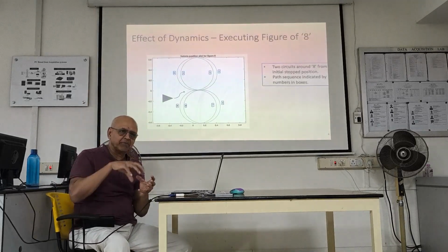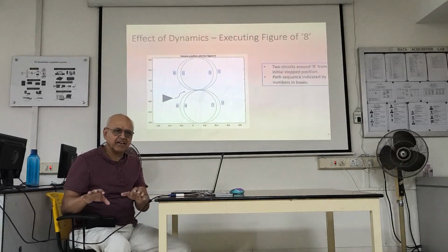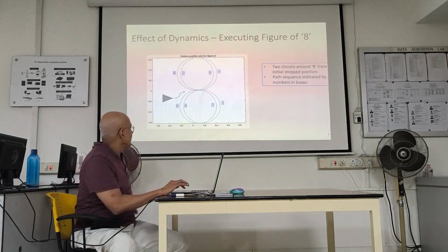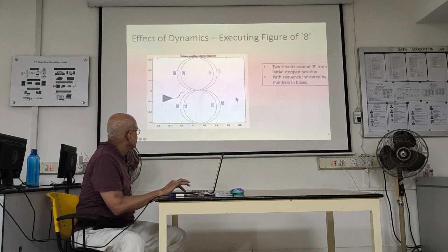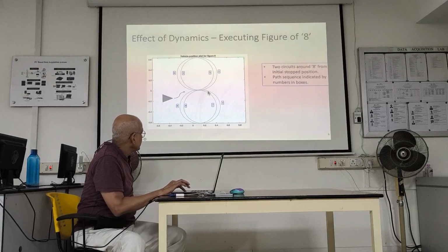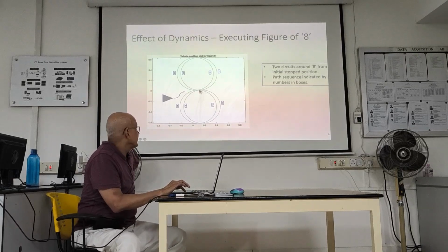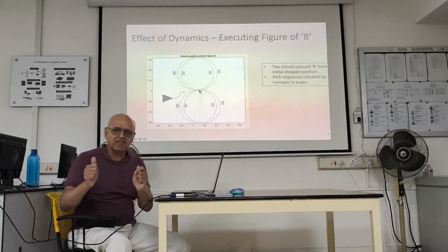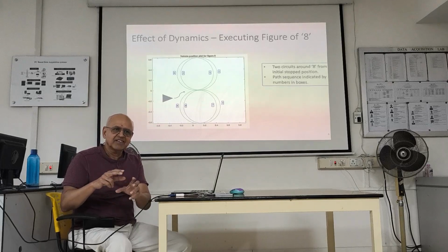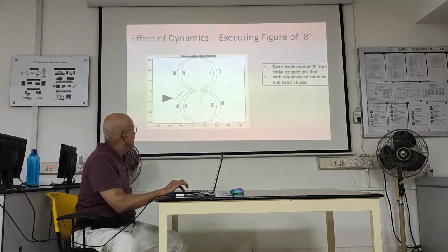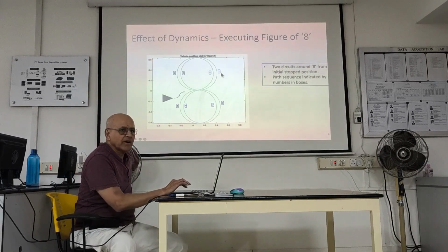Do you get it? Because I'm using the same radii. If I put different radii, it's a different matter. But right now I'm using the same radii. So they have to exchange velocities. So because they have to exchange velocities, you don't get the final circle immediately. So you get this circle. So 3, everything's steady here. You know, once it reaches the terminal velocity, it's steady, steady, steady, and then now you have to switch again. But now it's not the same switching. Initially you started from 0, 0. Now it's a switch, but it's not the same as 0 to target now. You just have to exchange velocities again. So that's why number 5 does not fall on number 1.